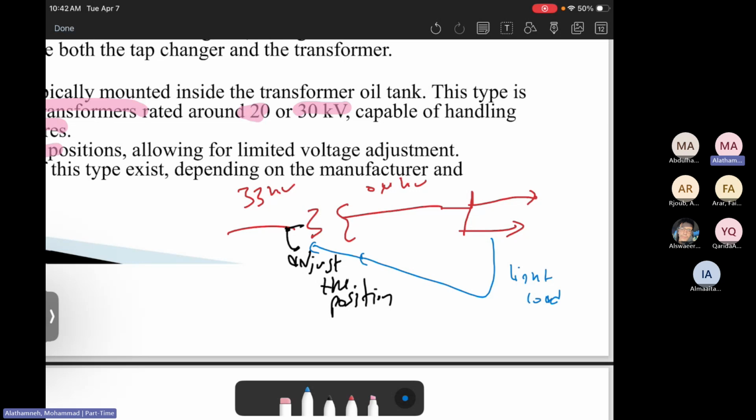By the customer complaint. So the customers can file a complaint and say, the voltage that I have at home is 250 volts. It's not 230. So what's happening? The power company or the utility will go to your home and measure the voltage. When they see the voltage is 250, oh, it's too much. Since it's too much, they will go to the transformer and adjust the turns ratio, lowering the voltage level for you. Okay? This is very common, and we can see it a lot